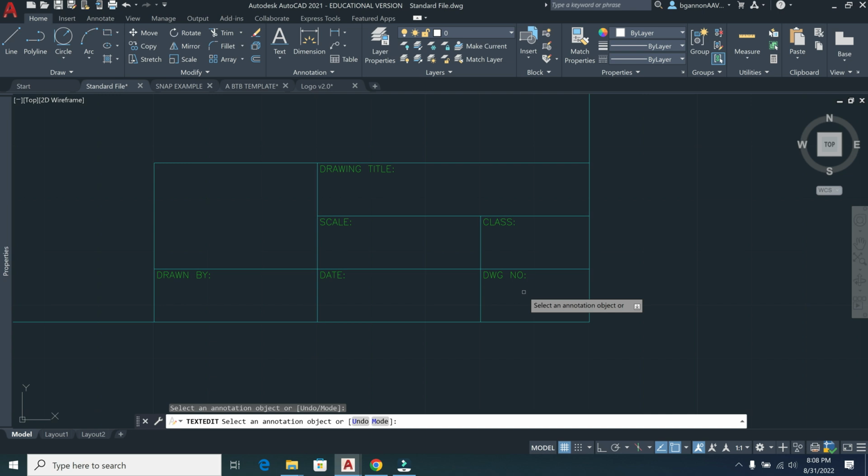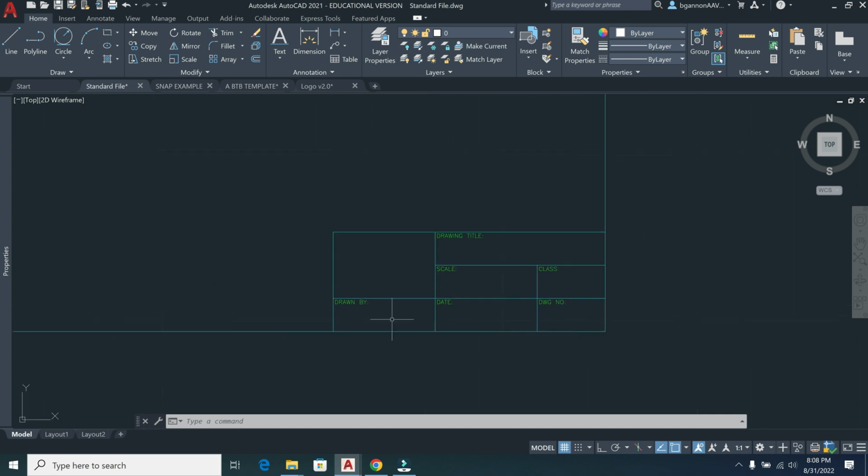And close that out. Make sure those are all in the text layer there, because the text layer, if you remember, is at a different line type and a line scale. So the thickness of that line will matter here. Next here, we've got a couple more things we're going to put in. So I'm going to copy this again, Control C or copy CO, and I'm going to paste it out here.